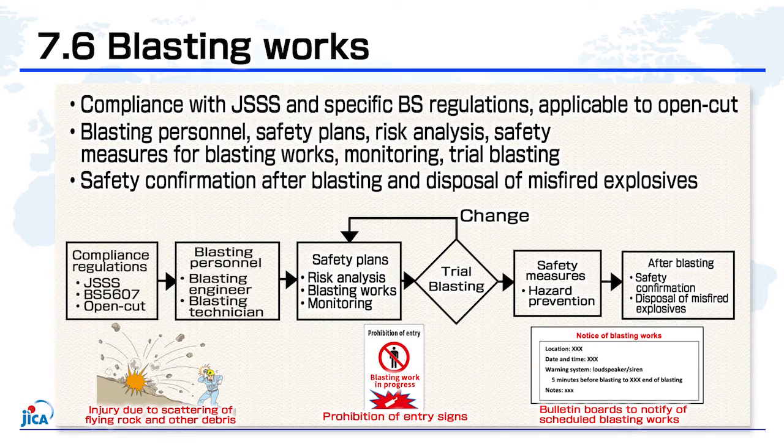Section 7.6 specifies safety requirements for open cut excavation by blasting. It covers preparation and implementation of construction method statements, safety plans and monitoring plans, compliance with specific BS regulations, placement of personnel, blasting safety plans, hazard prevention, handling of explosives, trial blasting, special measures, monitoring, safety confirmation after blasting, and the treatment of misfired explosives.